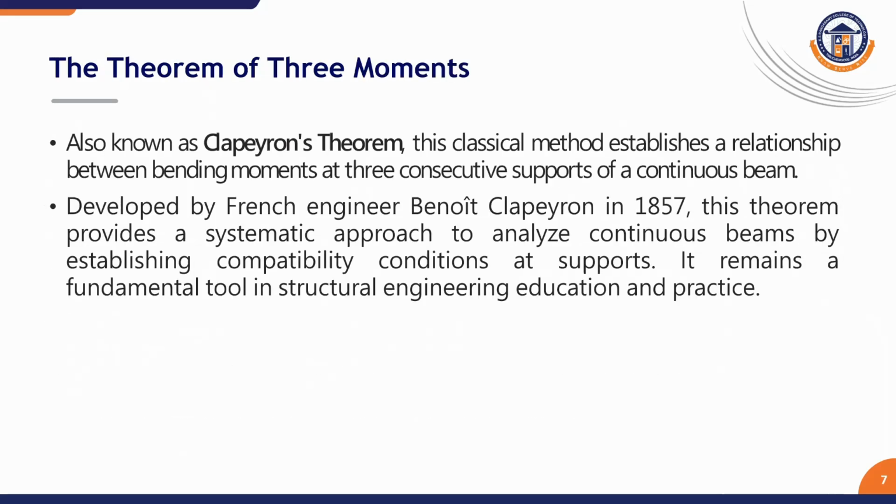Now we come to the core topic, the theorem of three moments. The theorem was developed by Benoit Clapeyron in the year 1857. It established a relationship between the bending moments at three consecutive supports of a continuous beam. The theorem is based on elastic behavior of material, small deflections, and constant flexural rigidity unless specified otherwise. The major advantage of the theorem is that it converts statically indeterminate problems into a set of solvable linear equations using compatibility conditions.